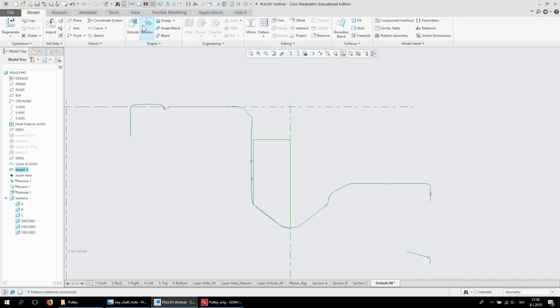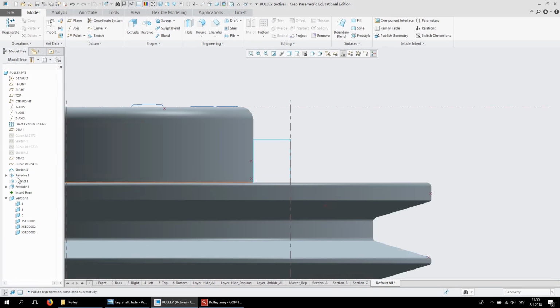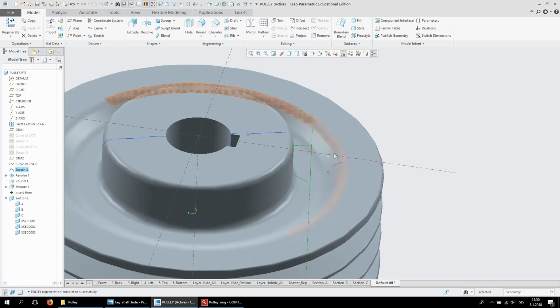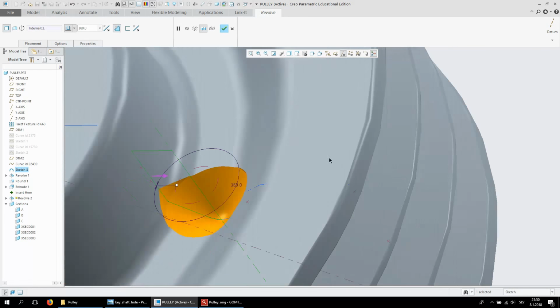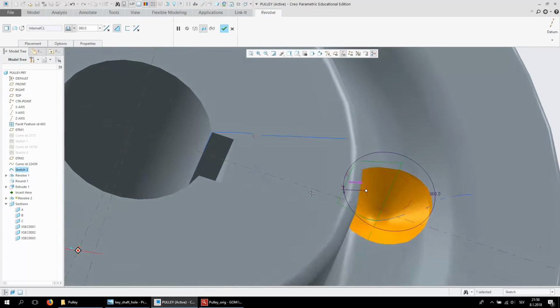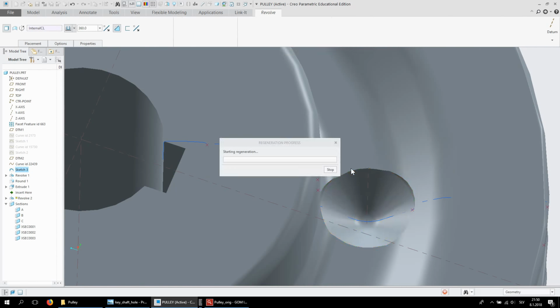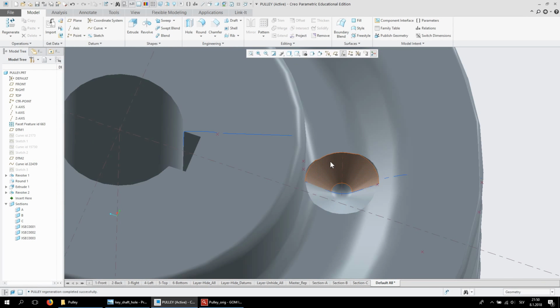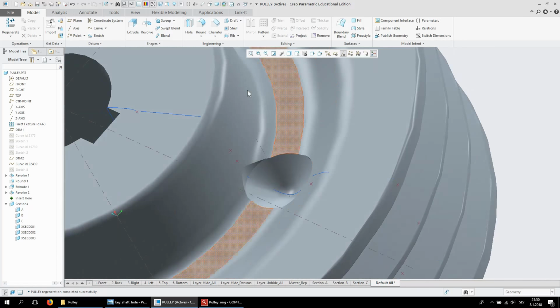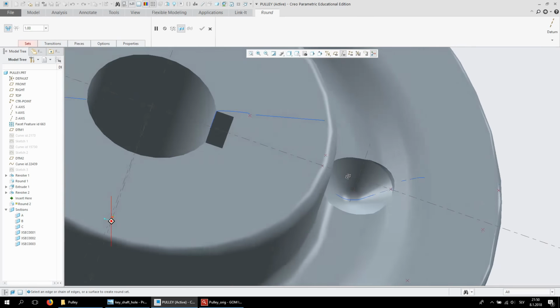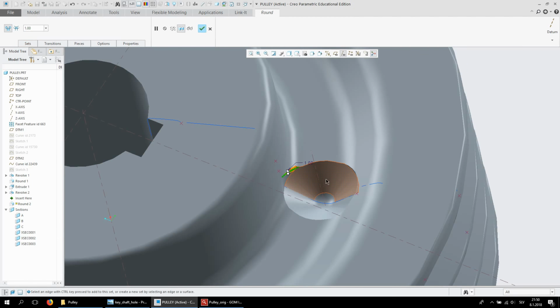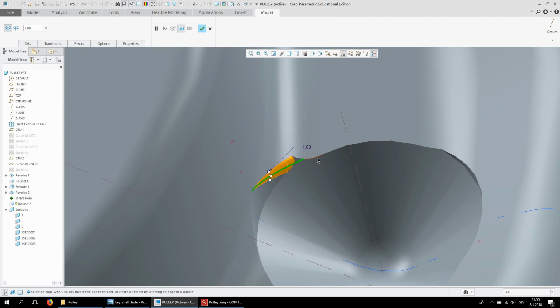So we have the sketch selected. Oh, actually we have to roll down, select the sketch and revolve and cut material. Yep, looks okay. So accept that, and now go to round. This is now so sharp, we should round it up a little bit.